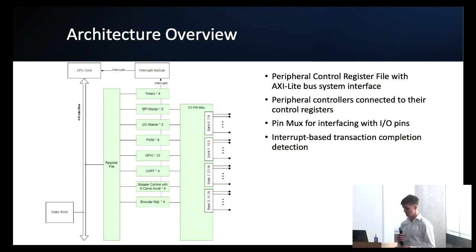This design is intended to be an encapsulation and a configurable entity. It's generator-based, with open source IP blocks, and it's fairly easily extendable to include any other peripheral controllers that you want. But the nice thing about this is that you have one point of access between the CPU and your peripherals, whatever that may be, which makes overall SoC design simpler and faster.